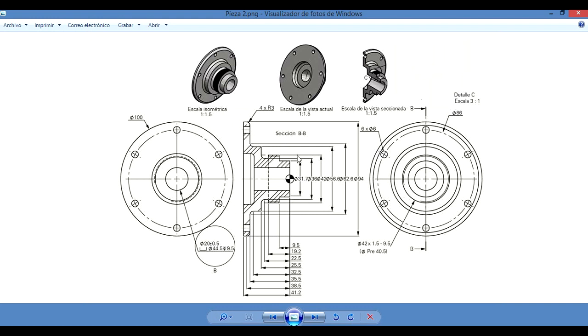Or we can do it the opposite direction by starting from this point and then continue with this and adding this level and this level. It can be done from both ways. I think the simple way is by starting from the base of the component. We're gonna start by making this part, this level. For this part, it's a circle. Here is the size of the circle, 100 millimeters for the diameter of the piece.